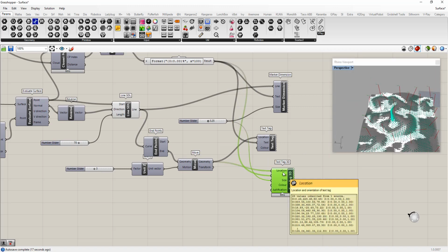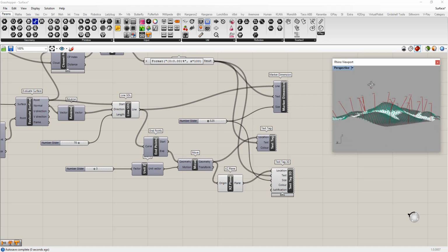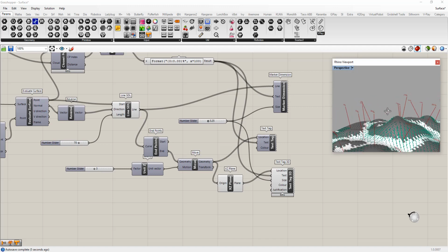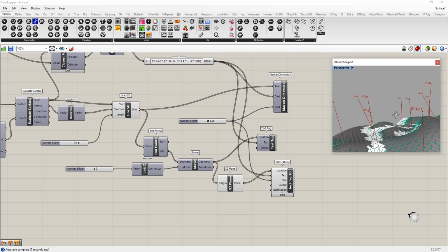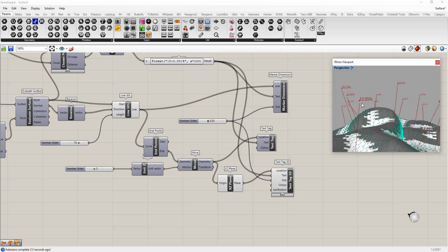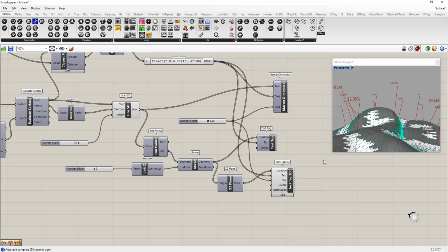So there's three-dimensionality to it. Now if we want it to face the same way, we can give it, say, an XZ plane at that location. But it doesn't face the camera, which might be useful in some scenarios. It also has a justification, so we can set it to being on one side or the other, depending on where you want it to be.